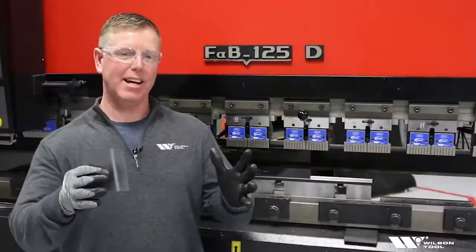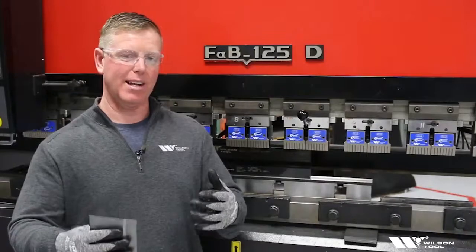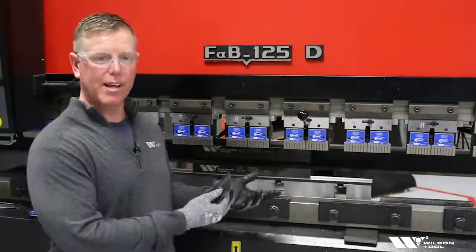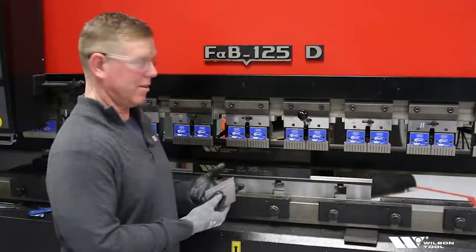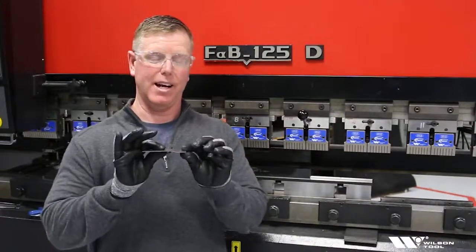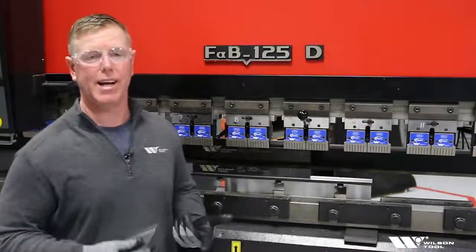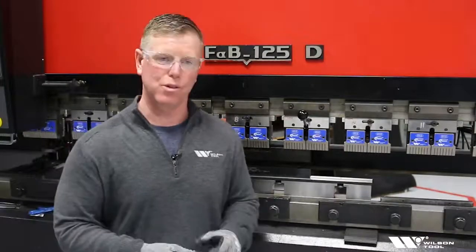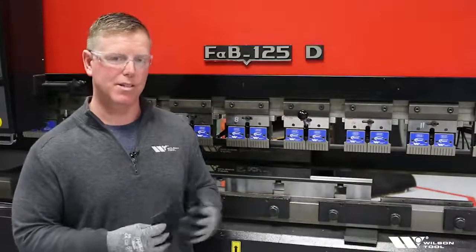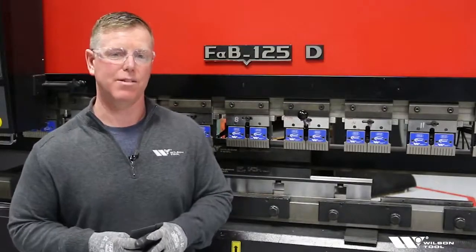So now we've taken that customer print, we've got a better understanding of whether they need an angle or a height or both. We've selected our tool. We potentially took a stock tool off the shelf and air bent that offset height that we need, and we've avoided contacting your tool room, having a special tool made up when they're busy. So you've got the tools now to potentially use a standard and still satisfy that customer print.